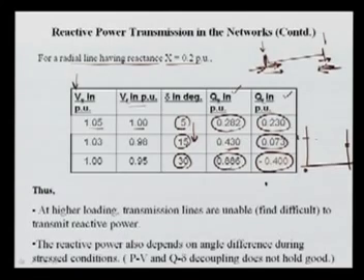What is happening in the voltage profile is that reactive power flows from higher to lower voltage. So your line profile will be like this, because we are maintaining the voltage, and the reactive power flows from here to here and again from here to here. In another case, it was 1.3 and here 0.98, the reactive power flows like this, meaning reactive power is flowing here and there is a lesser value there. In another case, it was 1, like this.